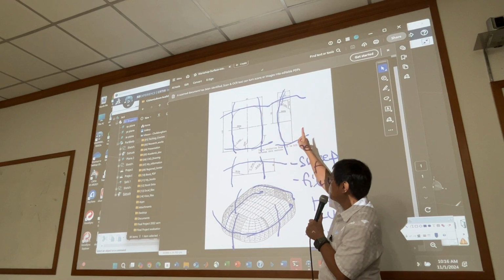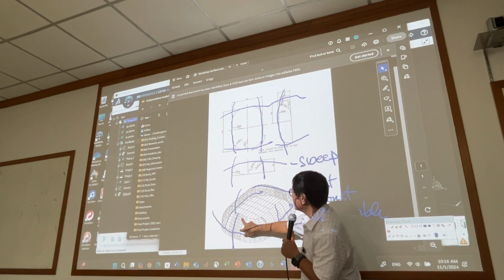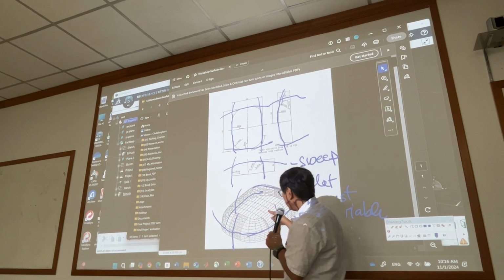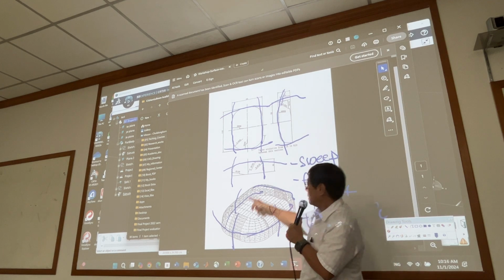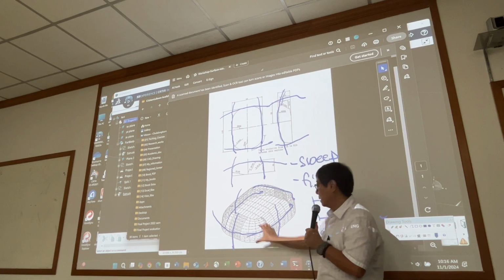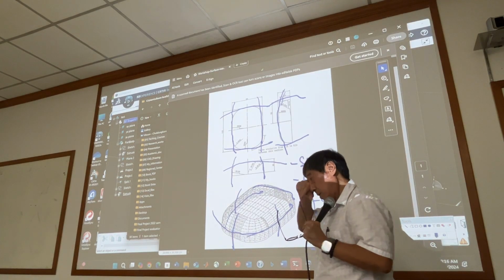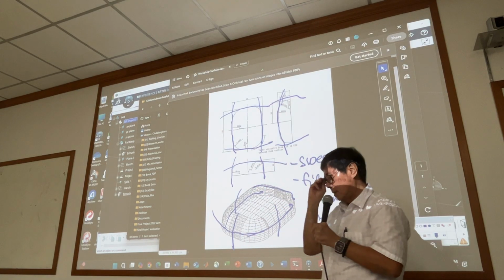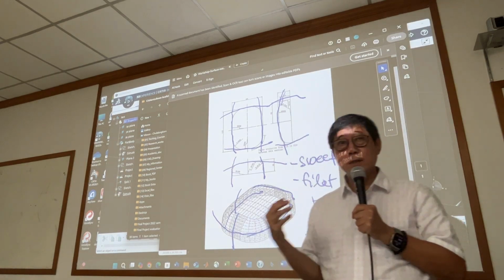Radius 30, right? This one has to be a variable radius fillet because this one is 20 over there. This one 15. That one 20, 15. This 20, this 15. Right? So this fillet we can do with variable radius fillet. Okay? You think you can do it?